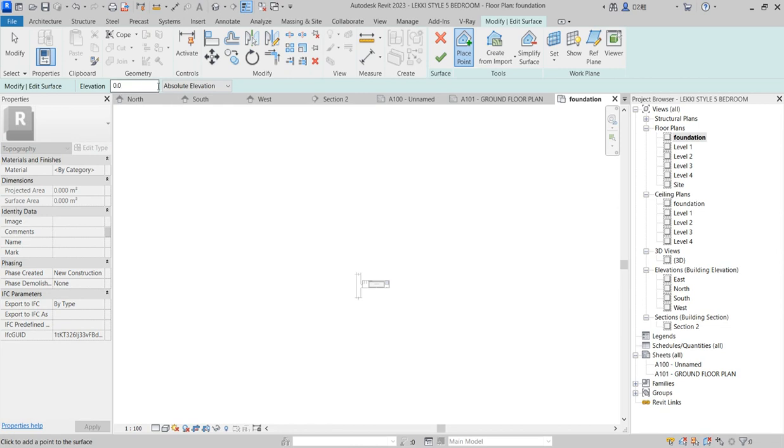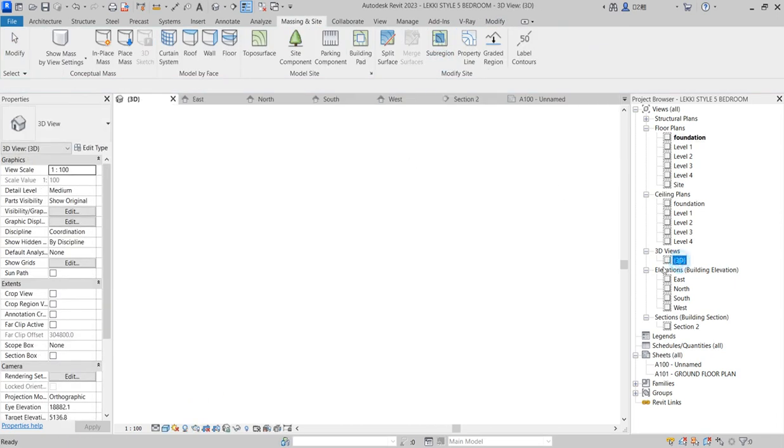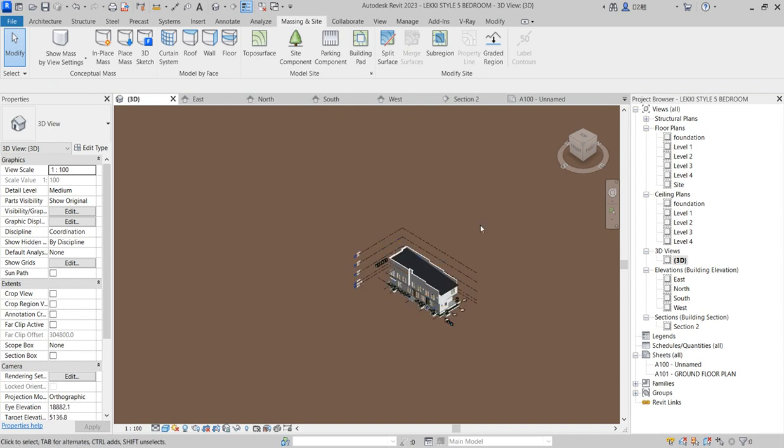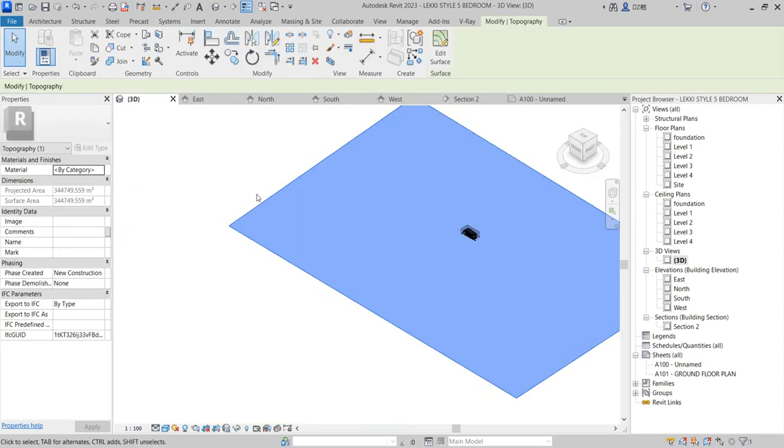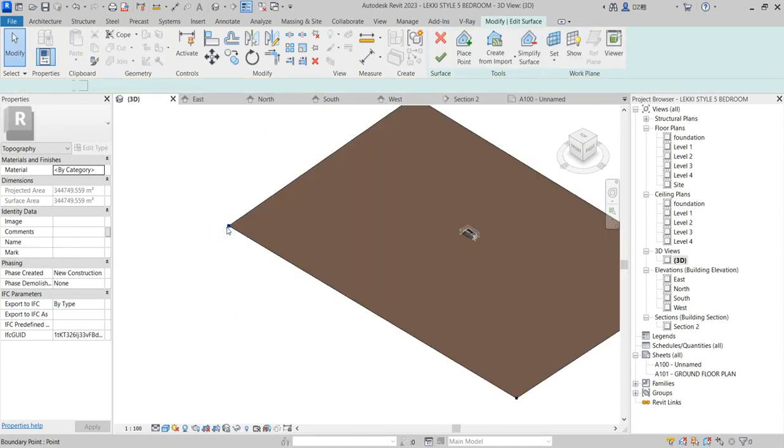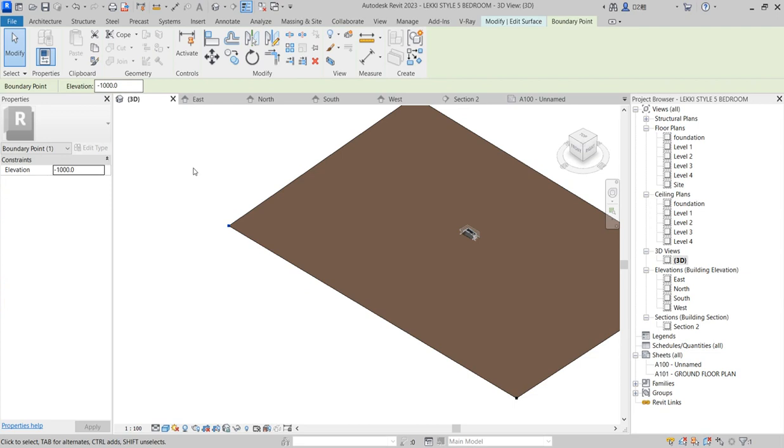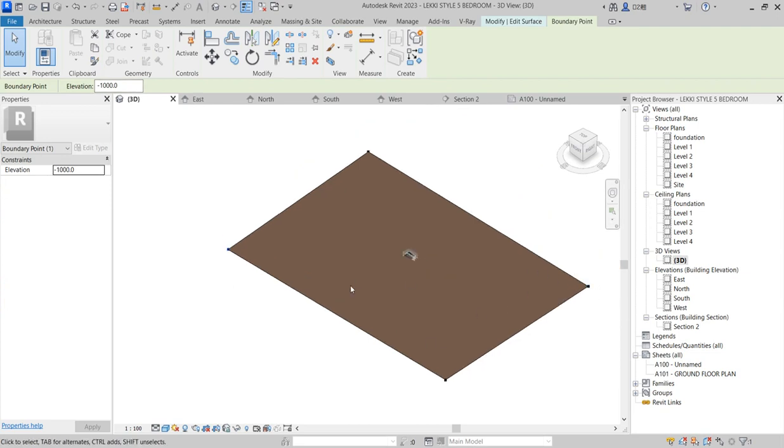The foundation land is minus the whole land of foundation, where the whole thing starts from -1000. So you type -1000 from here. That is the pure ground where the whole building starts from, and you drop it around these four corners. Then you click finish. When you click finish, you go and see what you have created, and this is the landmass you created. I did the elevation and checked all the marks, and you see that it's at -1000, and all these sides are at -1000.